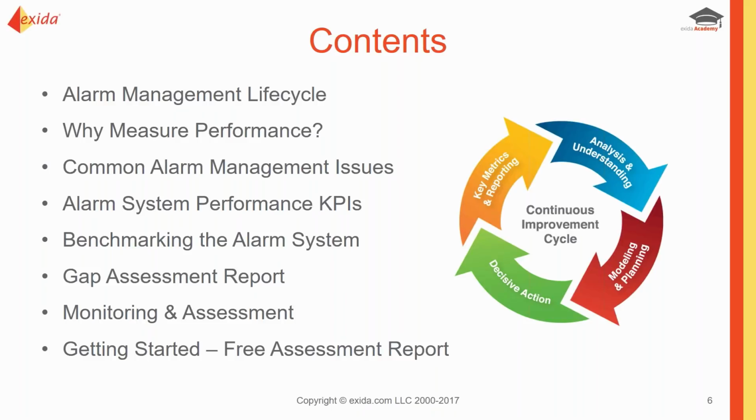We'll focus in particular on the portions of the life cycle that talk about performance measurement, talk about why you should measure performance, what do we judge performance against, how do we benchmark an alarm system, and we'll also look at some of the common alarm management issues that are the whole reason why we do the benchmarking and performance assessment, to view the status of the performance of the alarm system and to figure out how to make it better.